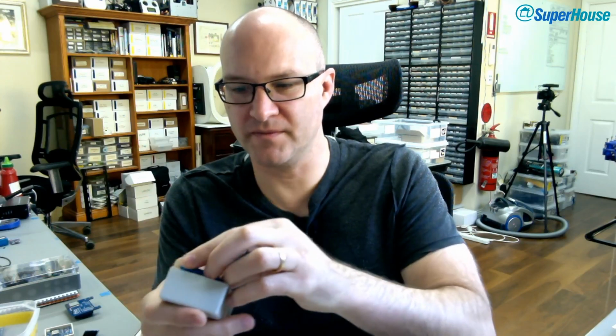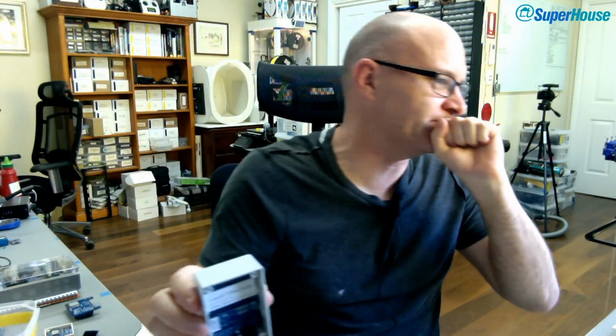And this board runs Tasmota. And then what you can do is use MQTT to pulse the buttons on the transmitter of the remote control. And then by clipping, you can see the ESP8266 module on the back there. So because it's designed to fit into this board, it should, if it all fits, just clip down and snap into place. And then the remote control transmitter is in the box there with it, and then you put the cover on and you have a nice little box that you just apply power, and now you have an MQTT enabled remote control for whatever device it is that you're wanting to hack around with.